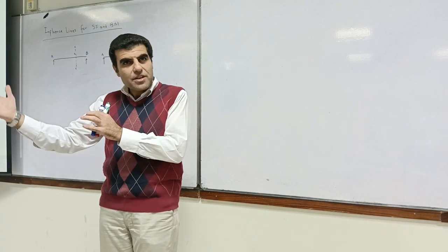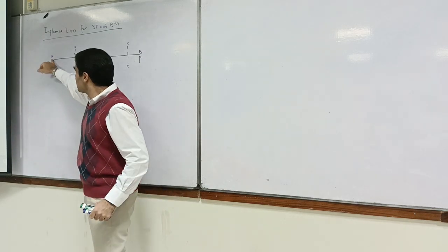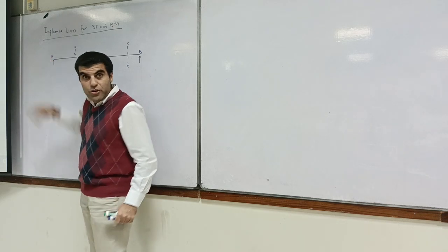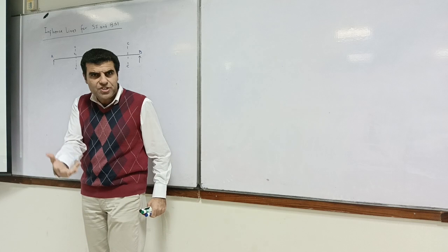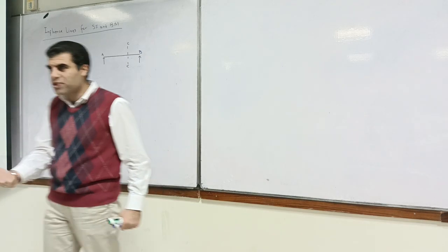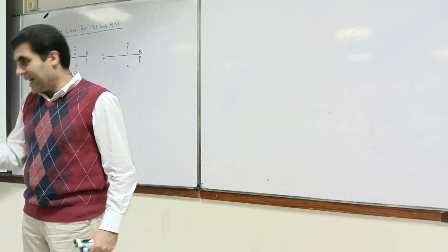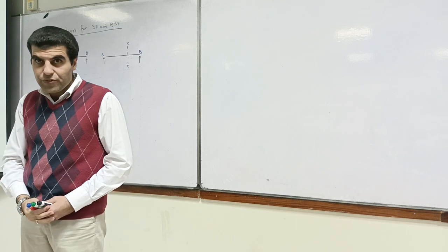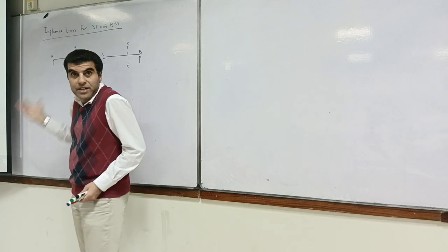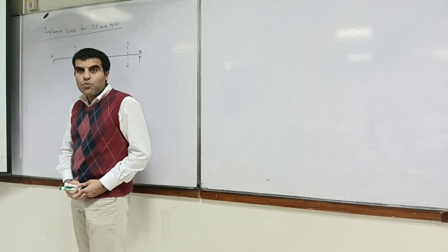No, reaction is different. Reaction is taking care of your support. You mean remove the support? Yes, exactly. If you remove the support, that's actually for reactions. That's not for shear force. Removing the support is not going to make any shear force over here zero. So what should you do?